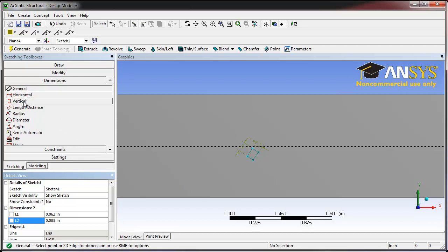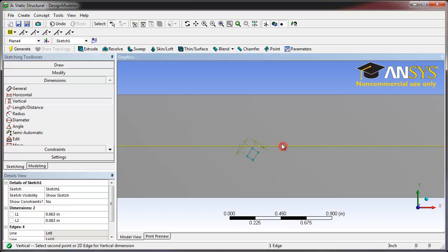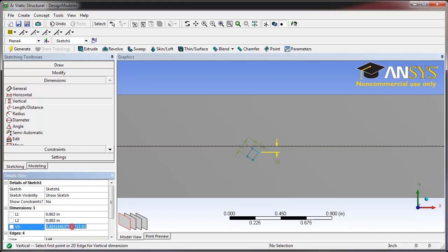Next, we'll define an arbitrary vertical distance between the center line of our crank and one of the points that we've just drawn. Set this to 0.25. It would be easy to draw an entire strain gauge rosette right now by adding 2 additional rectangles, one to the left of the central rectangle, one to the right.